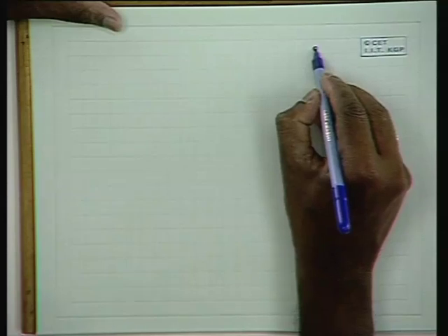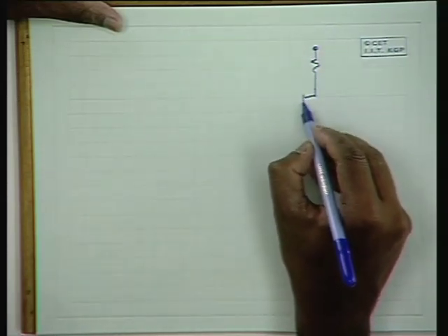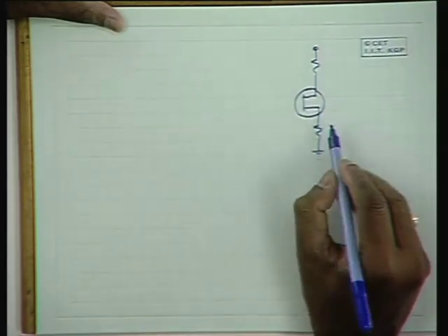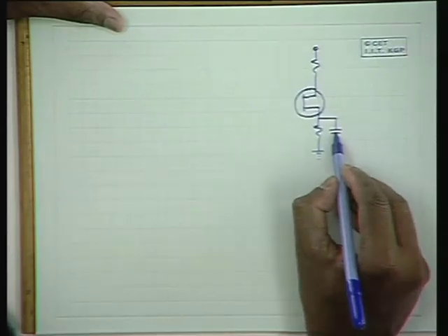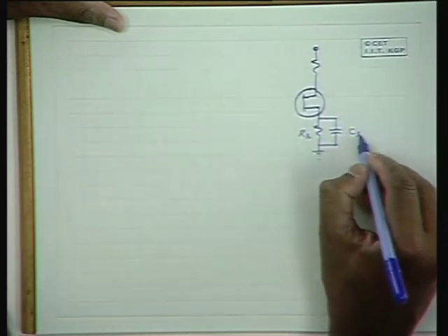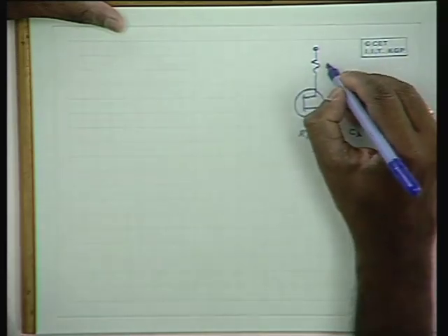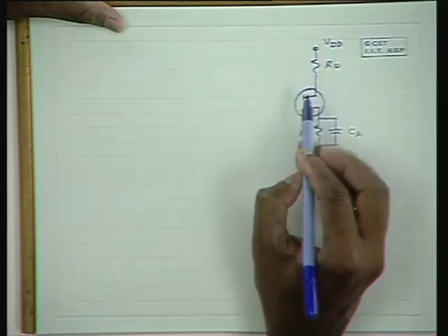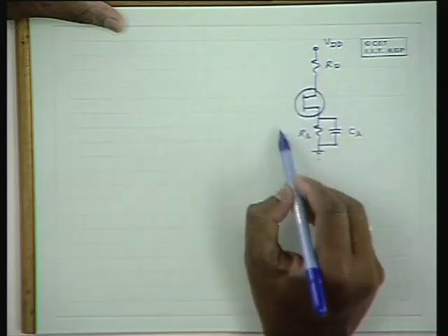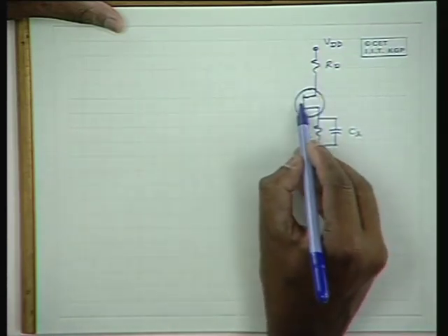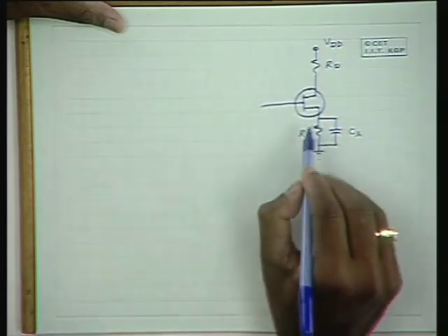Now, the same phase shift oscillator with a FET circuit can be given as shown here. First consider an amplifier with a field effect transistor with the source resistance. This is the bypass capacitance for the source resistance, this is the drain resistance and VDD. A voltage divider network can be added here if you follow a voltage divider network for biasing purposes. Please note that this does not include that. So, the biasing is through the voltage drop across RS.